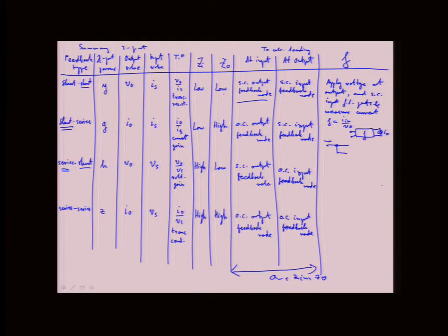remember there is this, something comes in and something feeds back to this node. So what's coming back? Current or voltage? Current, right? Because Kirchhoff's law does the summation for you at this node. Okay, so same as the case above, at the input, we're looking for current in order to extract this Y12F, right? So what do we do with that input? We short it.